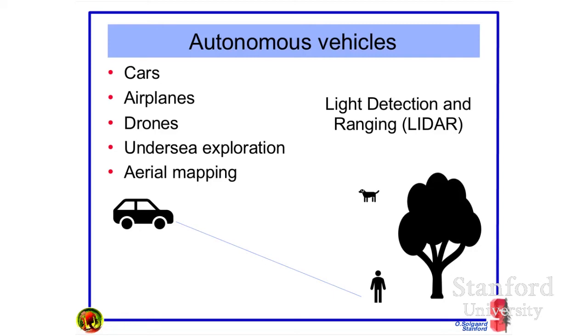Right now, the way most autonomous vehicles operate is that they have a LiDAR, which stands for light detection and ranging, and basically what I'm showing here is a laser beam scanning across the field of view, registering where things are. It's almost like a camera. It has a little bit more information because it can give you a little bit of motion information and so forth, and it also has maybe better resolution at a distance. But basically, you're getting an image of what's going on.